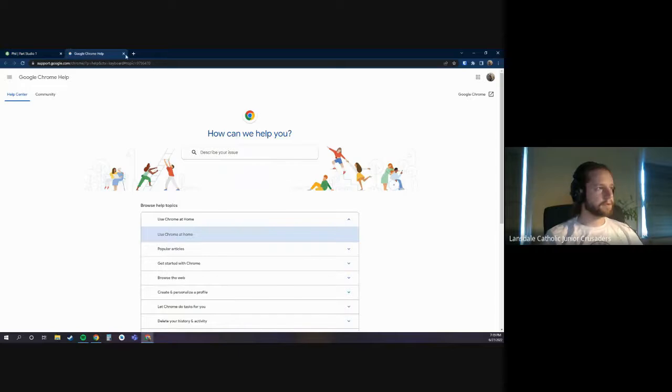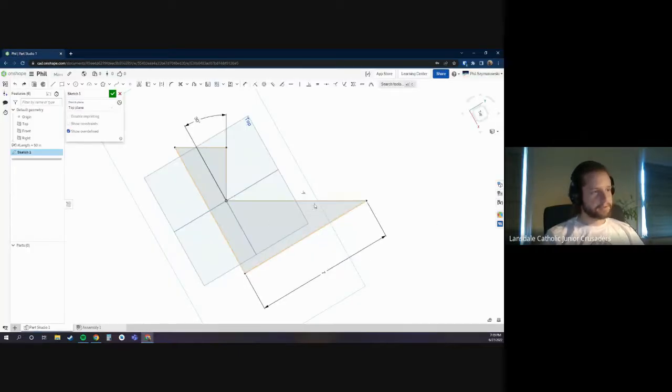Oops, I clicked F1 instead. So spacebar clears your selection. I just hit the spacebar and I clear my selection. And if I select a feature or if I select a constraint, the escape key clears the constraint. So you're going to be using escape and spacebar fairly often.